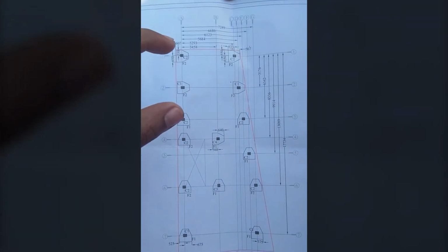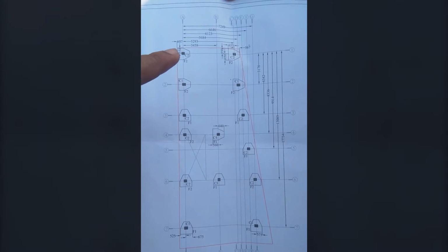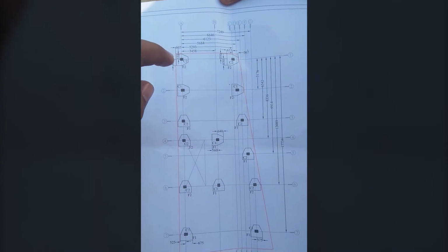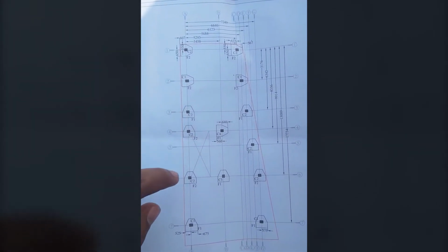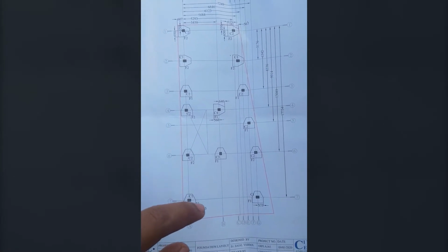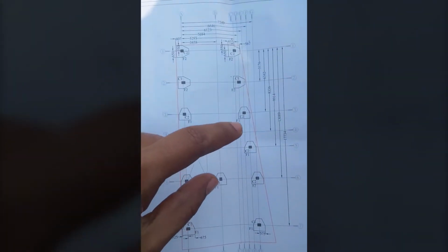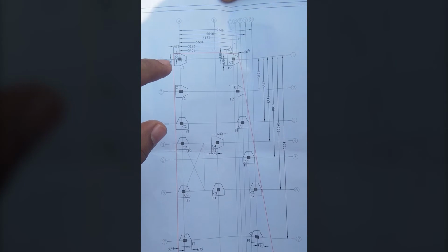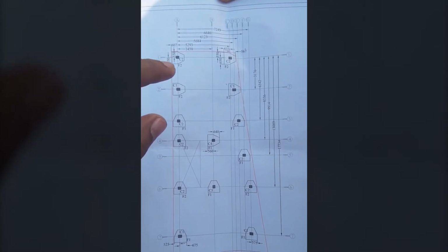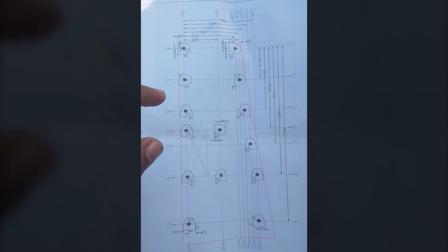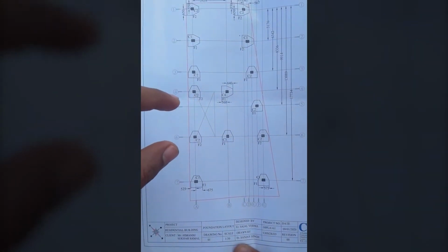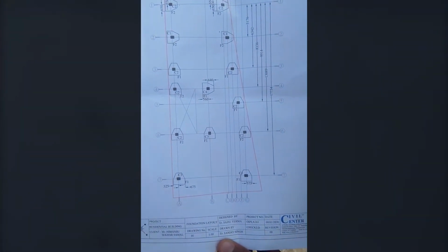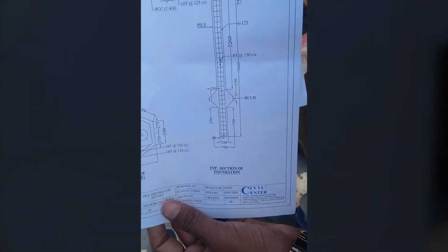It is best, after the topographic survey, that is after we get the plot dimensions accurately, then we can use a total station for the marking of these centers. After the marking of the centers of these footings or pile foundation, we can go for the excavation and then reinforcement binding and then casting of the pile foundation. So here was the pile foundation layout plan.